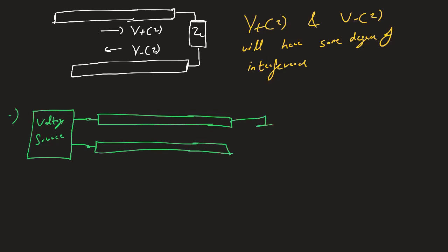And this is of course connected to a load ZL. This is an unknown load impedance. When you try to find an unknown impedance ZL, one of the ways is using a special type of transmission line which is known as a slotted transmission line.